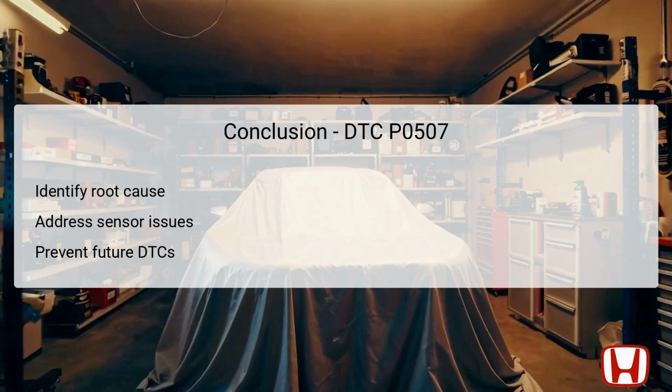In conclusion, addressing the DTC P0507 code requires a thorough understanding of the idle control system and the associated components. It is essential to identify the root cause, whether it be due to air leaks, throttle body failures, or miscommunication between sensors. Troubleshooting should take a methodical approach, starting with operational testing, followed by inspection and rectification of the involved components. Each step leads to ensuring that the idle speed aligns with the expected target values set by the PCM.